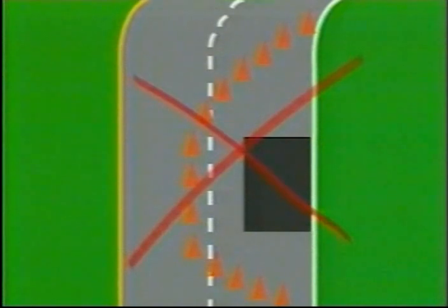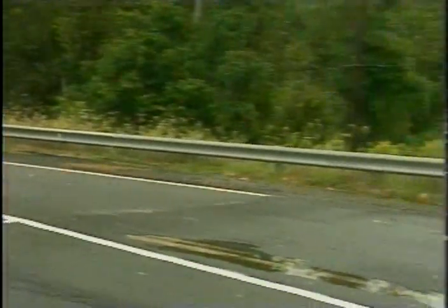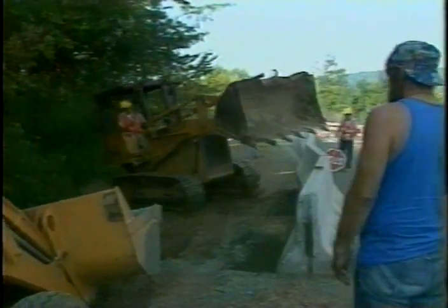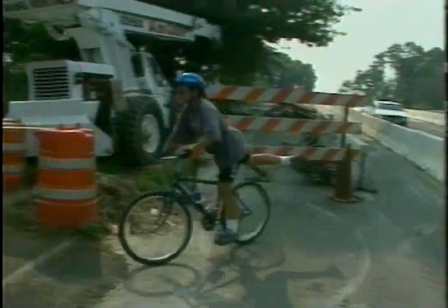Avoiding introducing severely restricted travel paths in the approach to the work areas or within the work area. Using lightweight, less hazardous channelizing devices and crash cushions on barrier ends. Planning so there are no conflicts with traffic and workers and equipment. Consider using portable barriers. Providing night visibility with floodlights, retro-reflectorized devices, warning lights, and pavement markings. Providing pedestrian walkways between traffic and work activities.